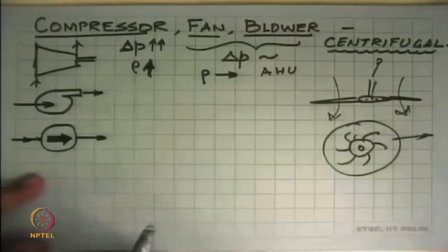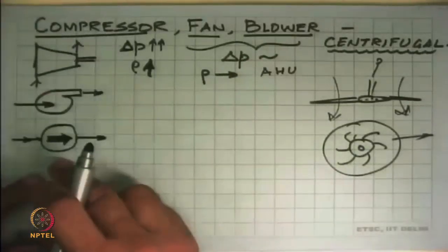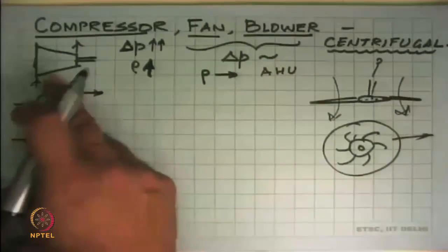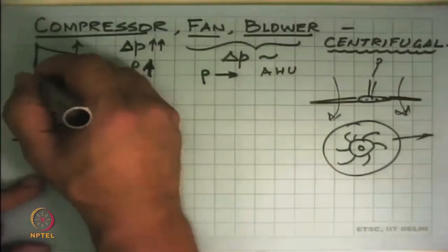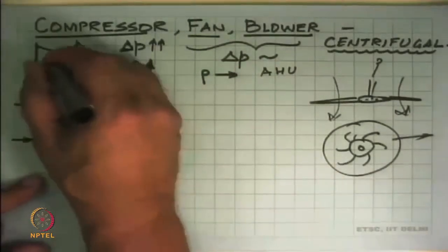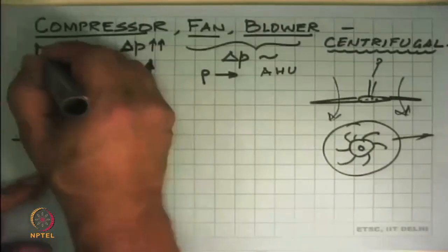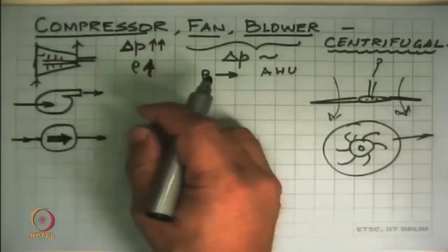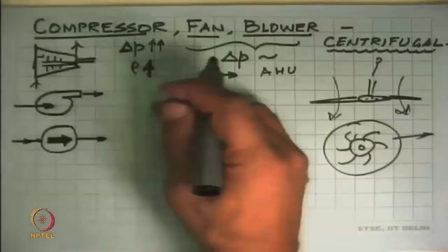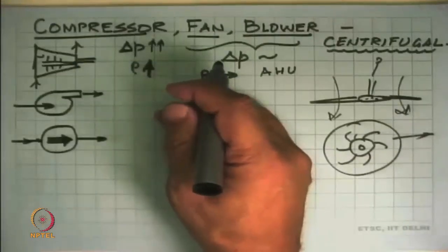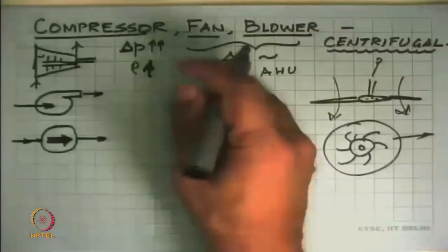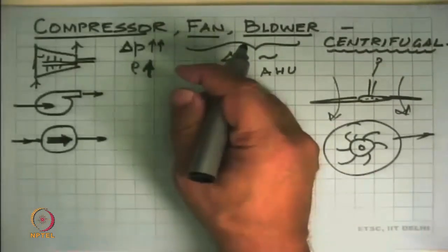In making schematic diagrams, we use three symbols over there. This means that the gas or air goes in. Inside this, there is a shaft on which there are blades. The air keeps flowing over this. There is a rotatory part which will give momentum to the gas, and a stationary part which will reduce the kinetic energy and increase the pressure without any work input or heat input.